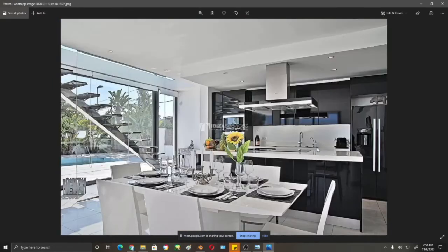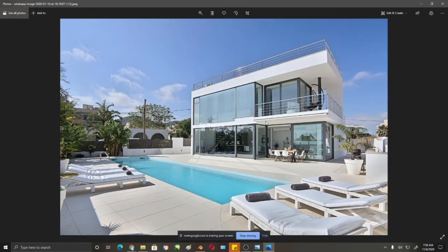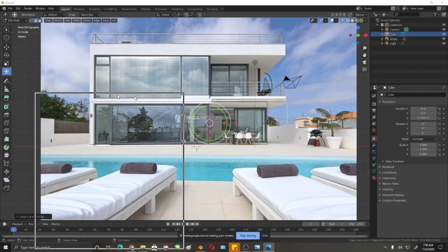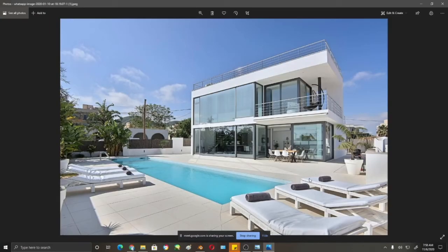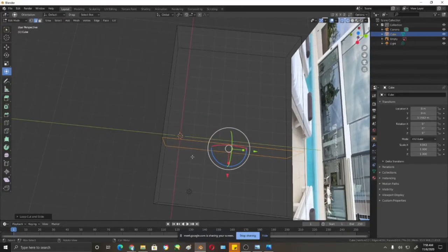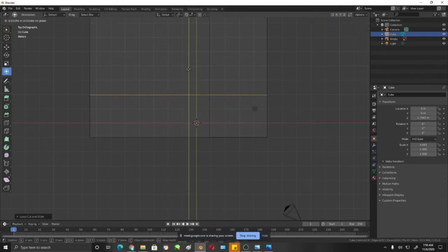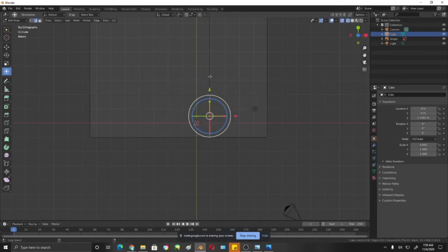As you can see, there's an inset where you could actually see the table and the chairs. So we need to cut into the cube so that we'll be able to put that inset for the tables and chairs. Press Shift Z in order to see the wireframe. Then add an edge loop. Then we're going to add another one for the front part of the inset.